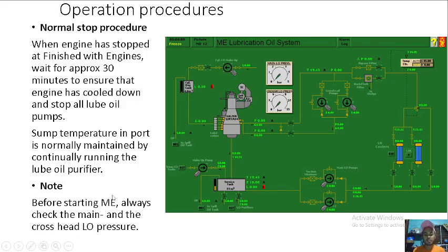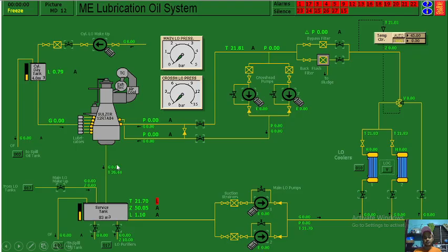So note, before starting main engine, always check the main and the crosshead lube oil pressure. It is very important to have a proper pressure for the main and the crosshead before starting the engine.